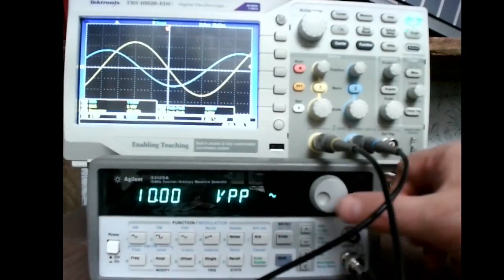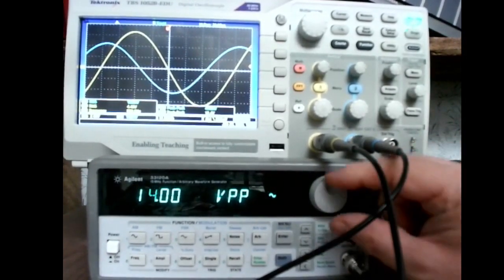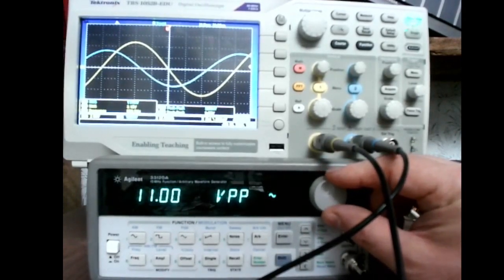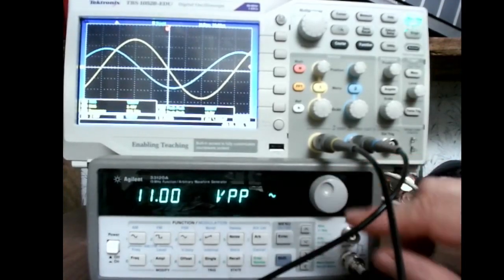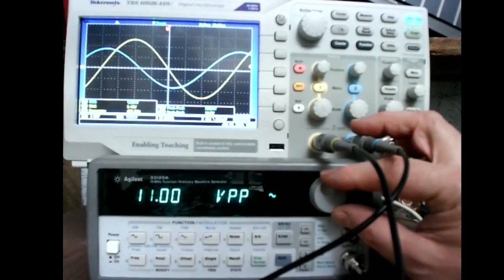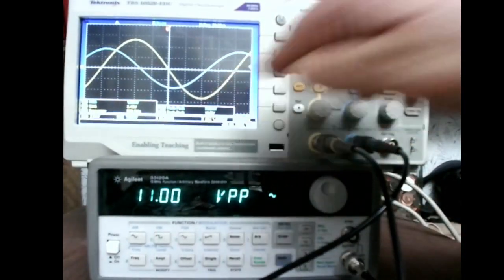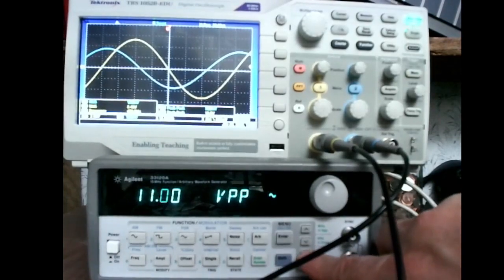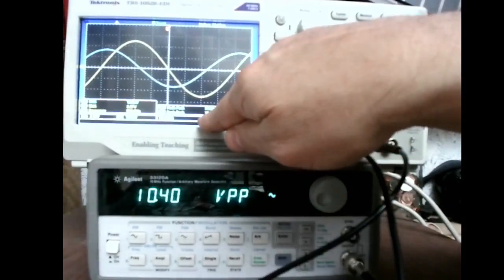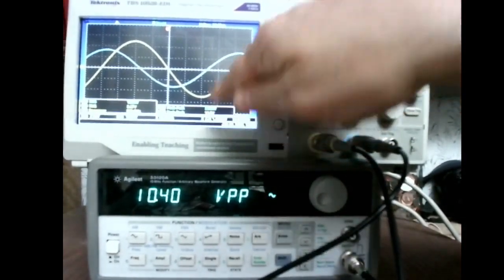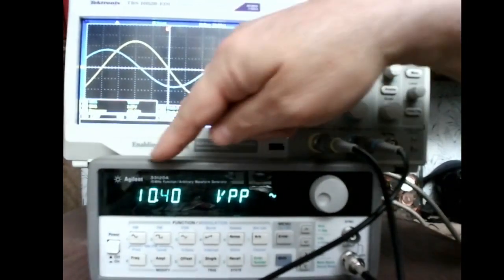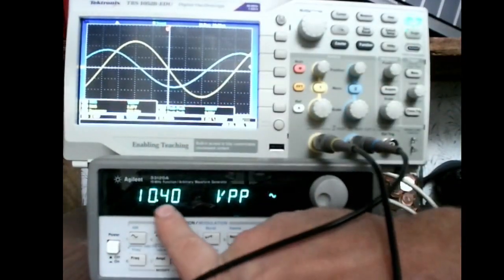Alright, so again, I can dial up my voltage. So if I was really looking for 10 volts peak to peak, I might have to bump my voltage up a little bit on there. Now see, I went up to 10.5, so I'm going to use this arrow and come over here so I can dial it down so I can get exactly 10 volts peak to peak on the oscilloscope. All right, so saying about 10 volts here.